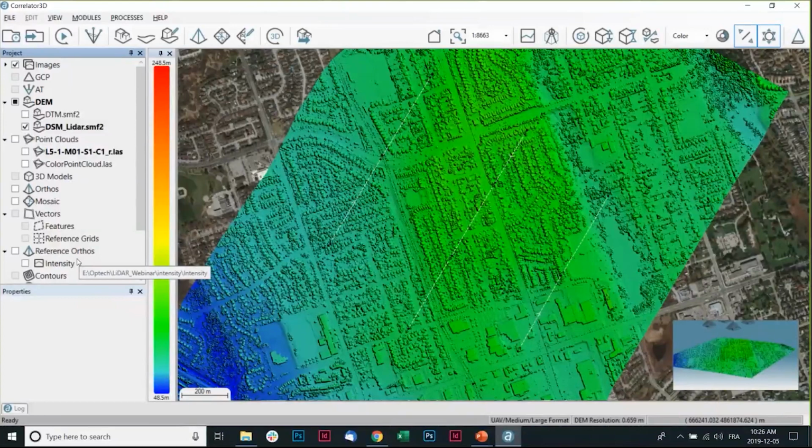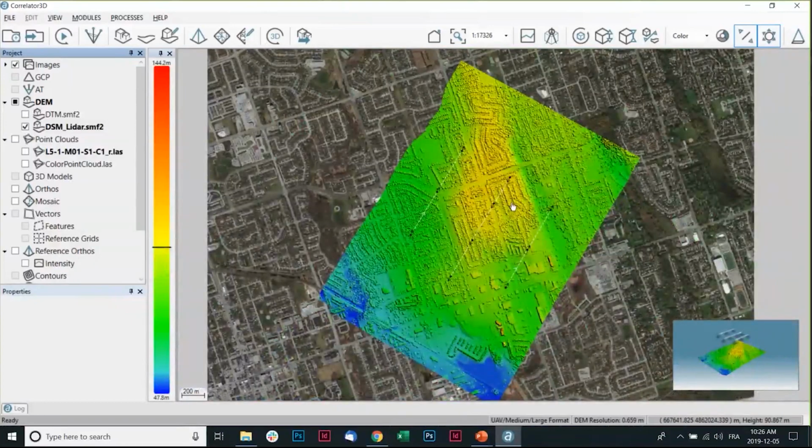The number of tie points that probably needs to be found between your intensity and your imagery should be roughly similar to what you would need if you were using GCPs. So you don't really need too many common tie points between both features. What's really important is that you make sure that the tie points that the software found correspond between both sources.